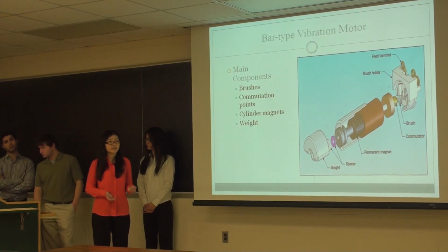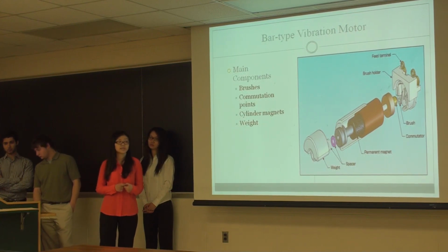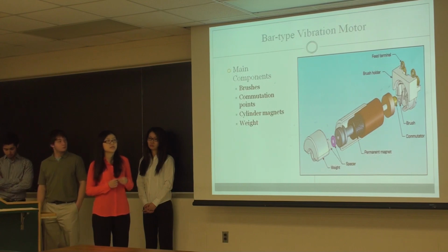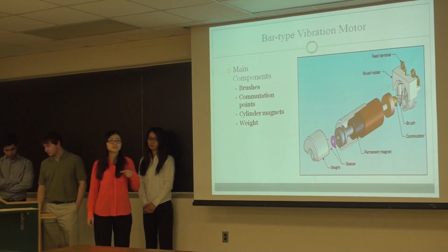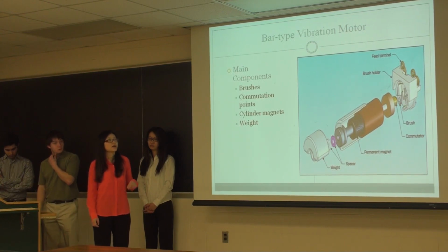This means there is an off-center weight attached to the motor's rotational shaft, and it will produce a centrifugal force while rotating. This unbalanced force will displace the motor, and the high-speed displacement will make the motor wobble, which is known as vibrating.